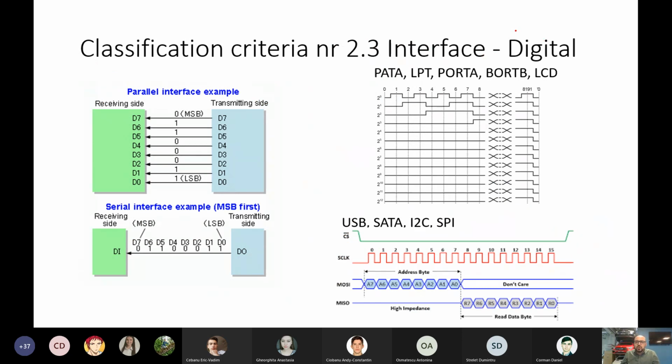because most probably you'll choose to use a digital sensor. What does a digital sensor mean? Let's say we have a kind of sensor, something in between, and we have a digital interface. A digital interface means we are already processing the signal, and it is providing already processed data.